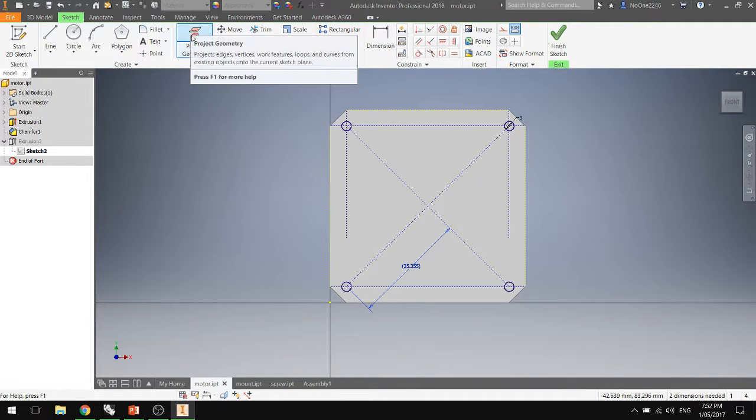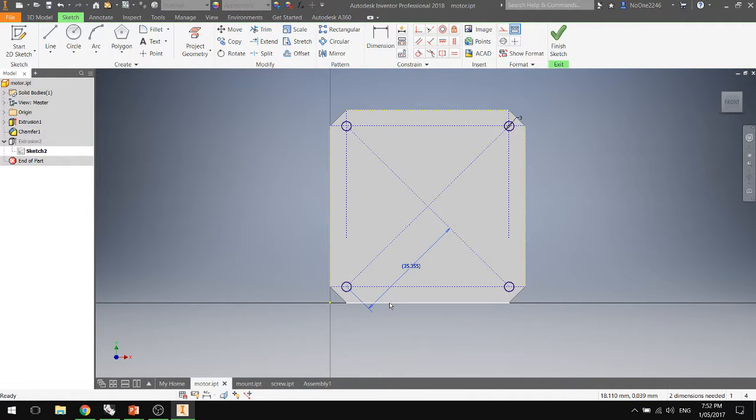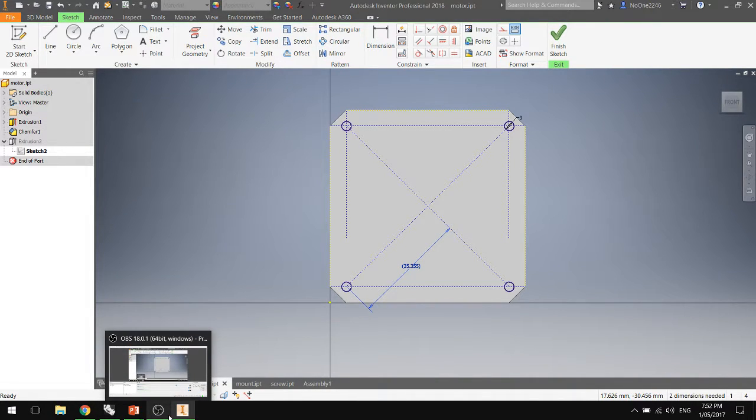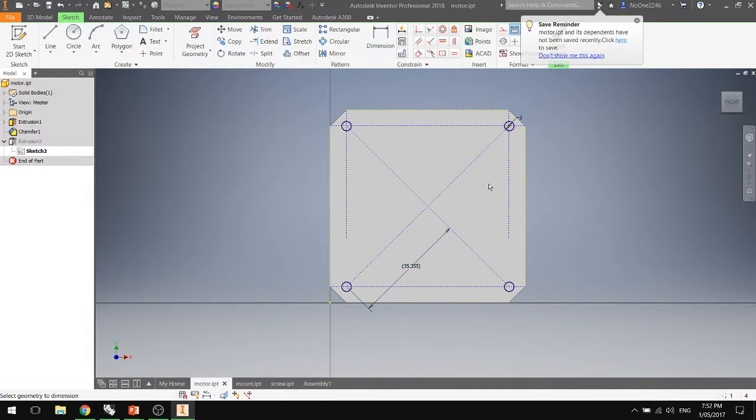I think it was under here. Oh, maybe. Was it on the project geometry that you did that? So how I got this, I just went back into Sketch. I created two construction geometries. So I created the two diagonals. Then I went dimensions. Dimensions. You can select a line to a point. There.